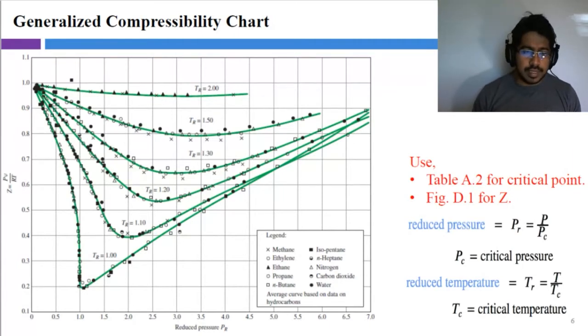And here there's a catch. If we just consider the pressure, then it's going to be different. What is high pressure for a given gas is subjective. What is a higher temperature for a given gas? We compare our temperature to the critical temperature, and then only we can say this is a higher temperature compared to the critical temperature.